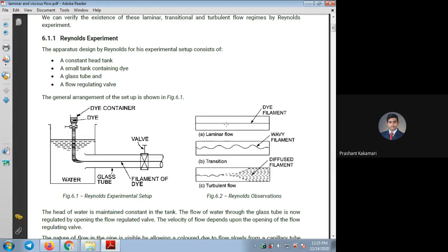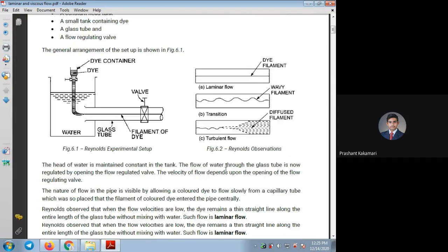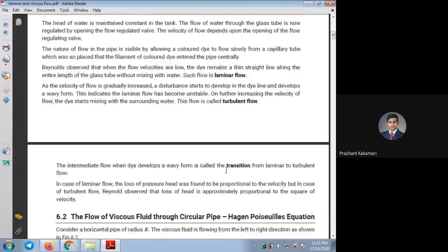So depending upon the path of the fluid inside the pipe, one can visualize without using the Reynolds number equation, just by observing through a transparent tube how the flow takes place. If you supply some dye, ink, or colored fluid which is not mixing with water exactly, then by the path of those particles one can explain whether the flow is laminar, transitional, or turbulent. So this is about the Reynolds number which you have studied already.